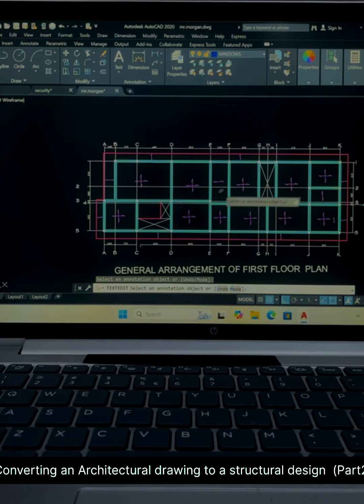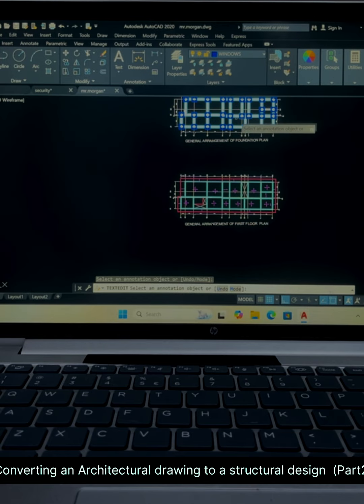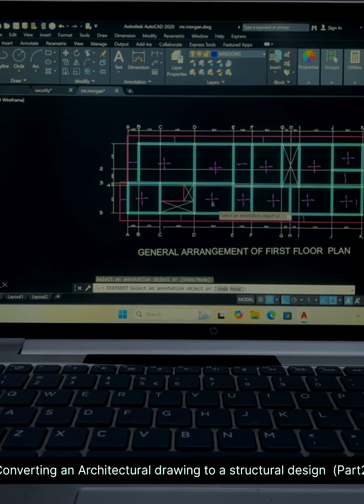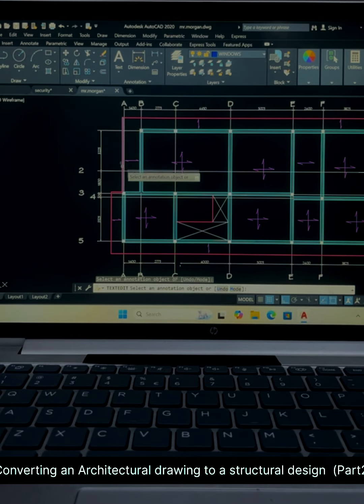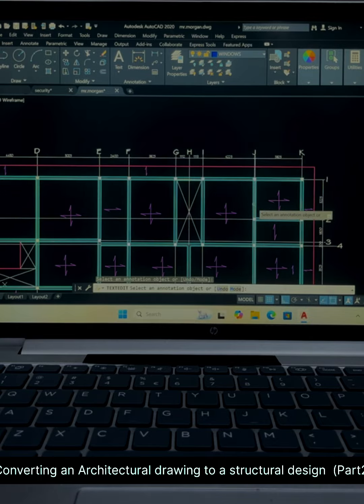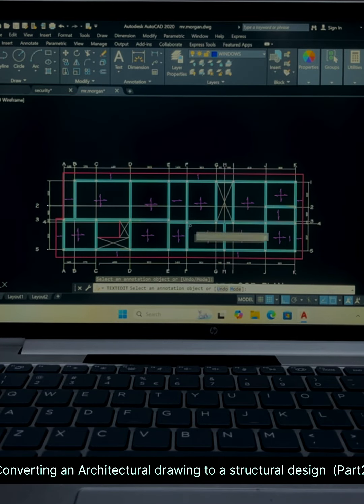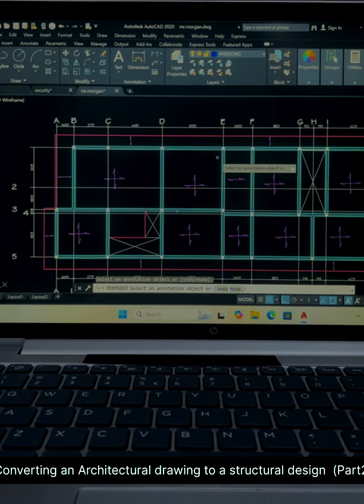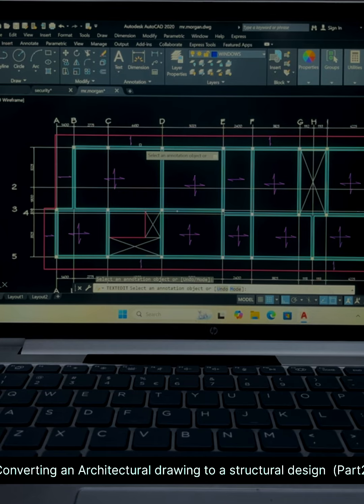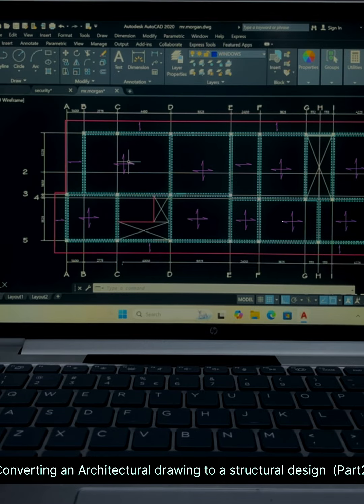Once we do the general arrangement, we can see, just taking a cue from the ground floor plan or the foundation plan, that in the first floor it shows that it has a cantilever, represented by this line. The pink color line is the cantilever around the building. So you show that. Then the major walls are connected by beams. You can see the beams.